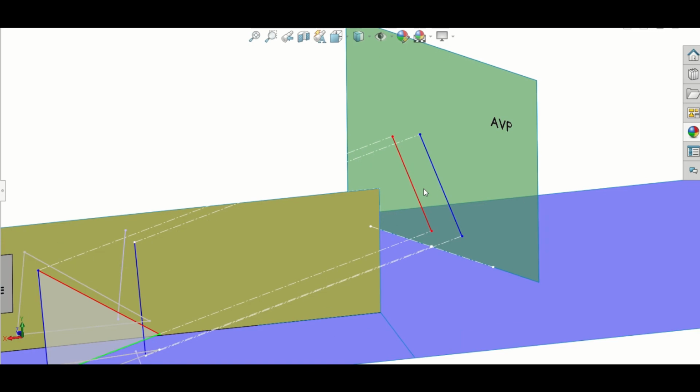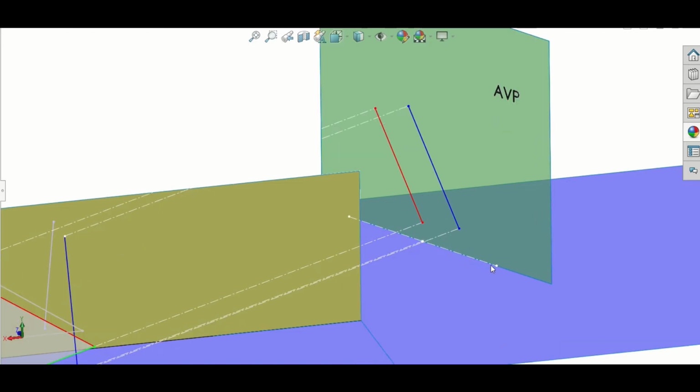And what we're doing from here on is using those to guide us in our next projection. So if we're asked for the shortest perpendicular distance, you look perpendicular to the lines. Or shortest distance is the same thing, you look perpendicular to the lines. If we're asked for the shortest horizontal, you look in line with the ground.